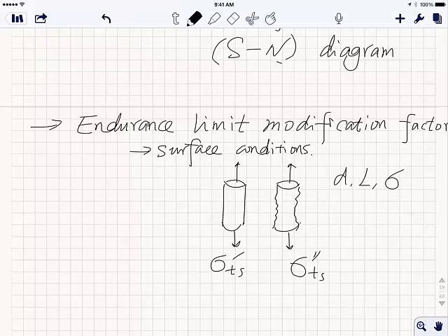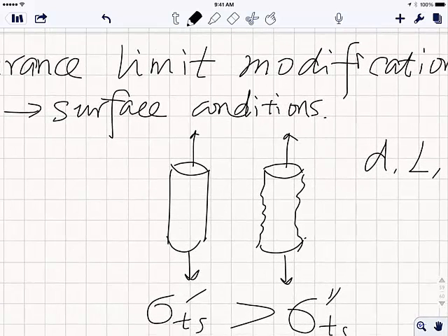Because if you look very closely at those rough surfaces, you are going to create a lot of small surface cracks, which will induce a lot of surface stress concentration. See here, this is an exaggeration of a realistic case. I have a crack on the surface.